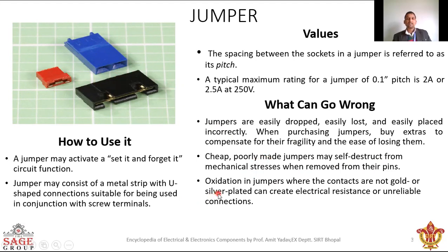And the third is oxidation: in jumpers where the contacts are not gold or silver plated, it can create electrical resistance or unreliable connection. Okay, so these are the basic three points which we have to take care of.